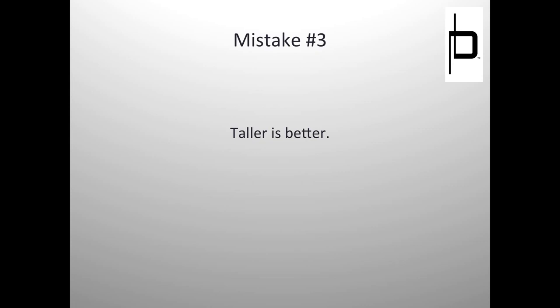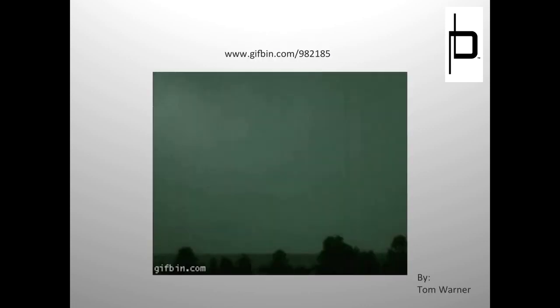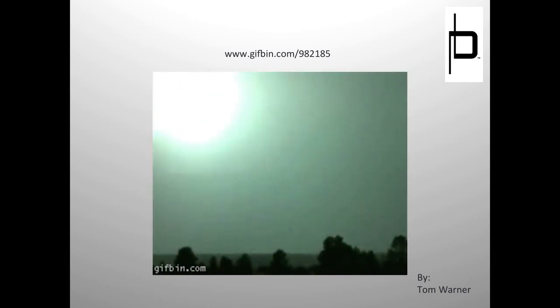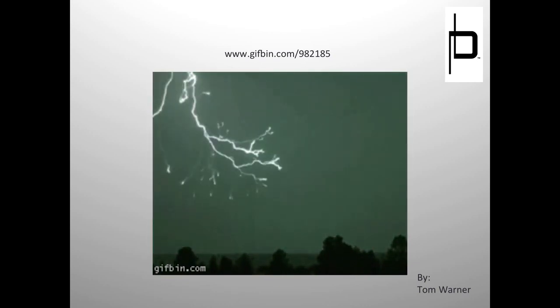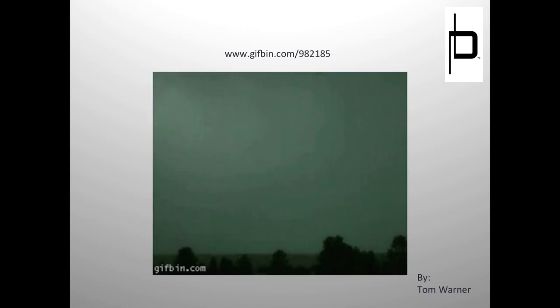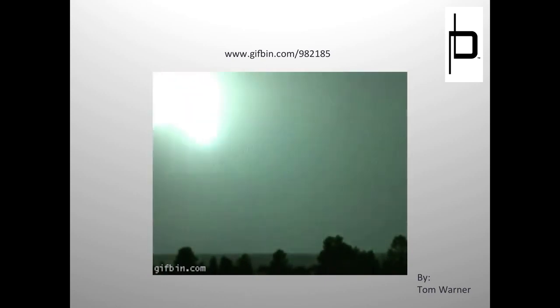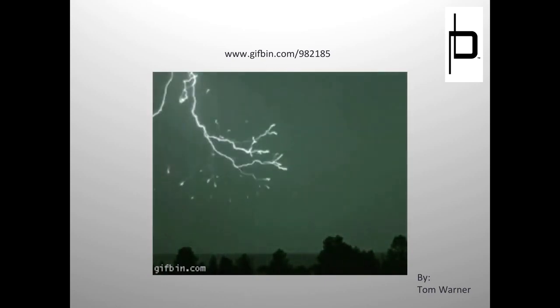Okay, so mistake number 3: taller is better. We talked briefly about this earlier. Remember, this video proves that step leaders can go sideways, can even come back up. You see some of these step leaders going up, certainly a lot going sideways. So we can't just assume top-down strikes for everything. That's not the right way to do this.